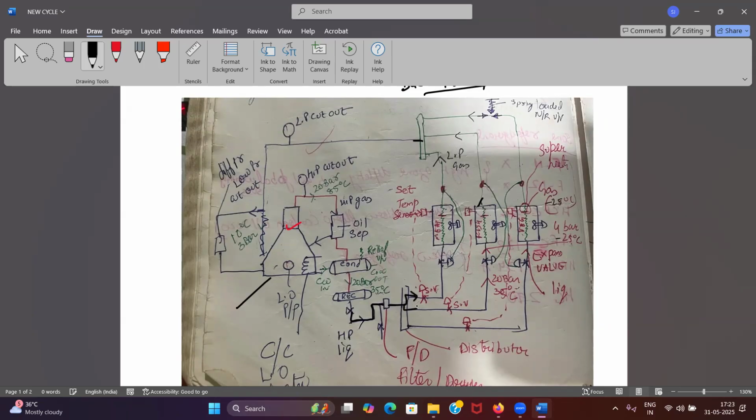I want maximum refrigerant to go to my these two lines. Do you agree? To cool my meat room and fish room. I want very less amount of refrigerant over here. How will I do it? If I create back pressure onto my system, it will close my TEV accordingly. Less opening, P2 pressure is increasing by creating back pressure.